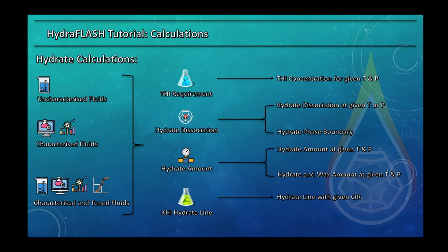By hydrate safe zone, I mean the zone where hydrates are not stable, and in a stable zone, at those temperatures and pressures, hydrates are stable. It doesn't mean that at those conditions hydrates necessarily form, but it only indicates that at those conditions hydrates are stable.